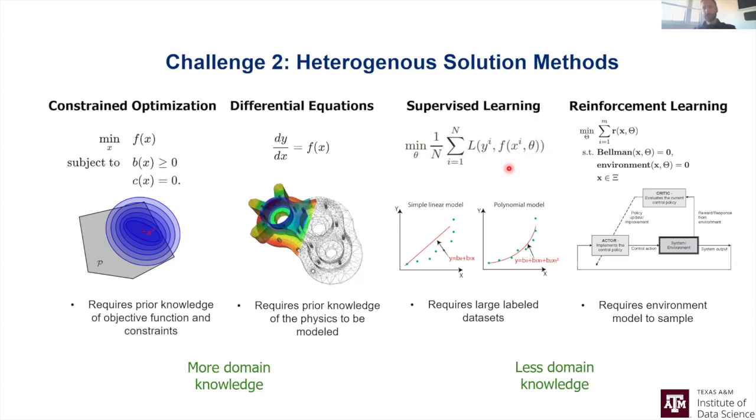For decision-making schemes, where we cannot represent our system models in differential equations or as constraint optimization problems, but we have some digital environment, or at least we can interact with the real system on a sampling basis, reinforcement learning is a very powerful methodology that allows us to learn the fitness function of the controller that is co-created and optimize the actor, the control policy, to control the desired system to steer different reward functions or reward signals.